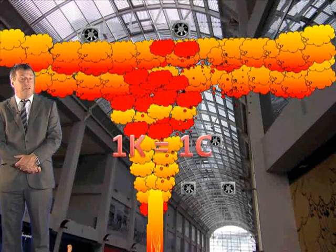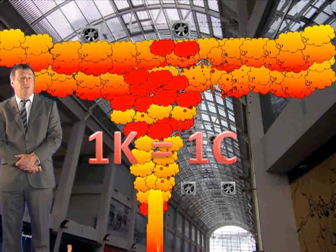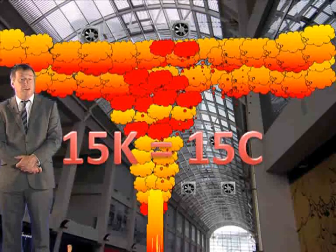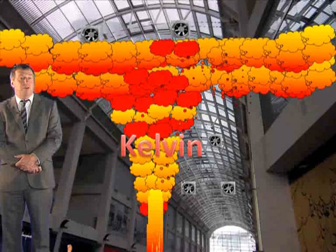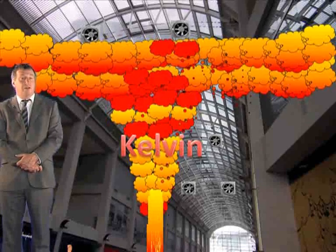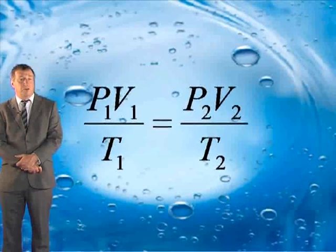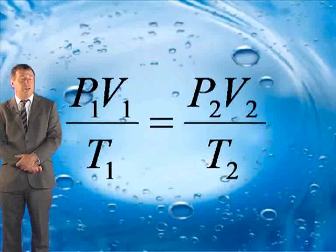As I mentioned earlier, it should be noted that theta can be given in units of Kelvin or degrees C, and this is because it's a temperature rise or a difference in temperature. 1 Kelvin is equal to 1 degree C, so a difference of temperature can be expressed in either unit by giving the same figure. That is, a temperature rise of 15 Kelvin is the same as a temperature rise of 15 degrees C. The average temperature of the smoke layer should be expressed in Kelvin. This is partly because some of the equations that use this result make use of the principles expressed in the general gas law, and this law is concerned with Kelvin and not with the more arbitrary degrees C.